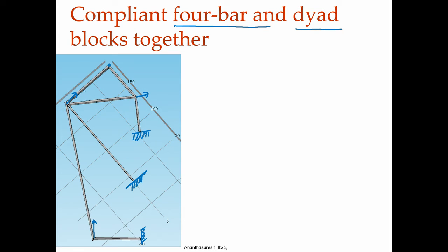Then you can see that if you consider this as a rigid body, which it is, okay, and so is this, it should also be rigid, relatively rigid as we just talked, compared to the other segments. Here this is the compliant segment, compliant segment, compliant segment, this is rigid and this is also rigid. Okay. When it is rigid, we can see how this point moves, because if that point is moving like that, we have this line, okay, and if this point is moving like that, we have this line. Now this one here will be our instant center of rotation.